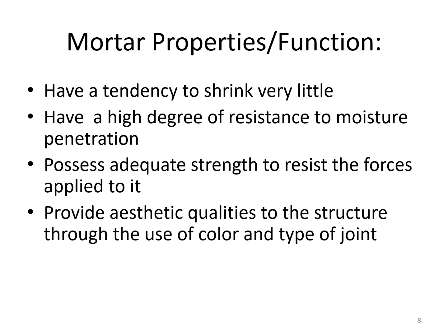So some of the properties and functions: well, mortar should not shrink very much at all. It needs to have very little shrinkage, otherwise cracks would form in between the bricks and voids, and then moisture would get in, and if there's a freeze condition, that even expands the joints more and we get a lot of damage. So the mortar also needs to have a higher degree of resistance to moisture penetration. And that's what I was talking about earlier, where the acrylic polymers help even reduce that further. But definitely, the Portland cement already has a good amount of properties for preventing moisture penetration.